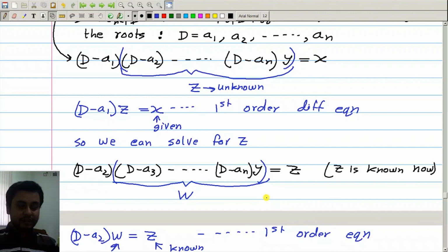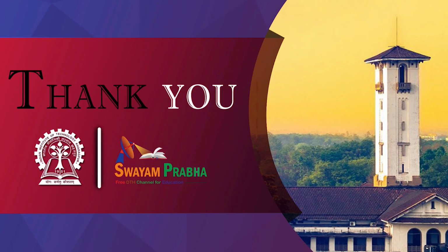Okay, that will be a very important thing to learn, because if we know how to calculate output when the input is an impulse function, that means we can calculate impulse response, and from that we can calculate the output for any arbitrary input signal, because any arbitrary input signal can always be written as an integral or sum of time delayed delta functions. Thank you. See you tomorrow.